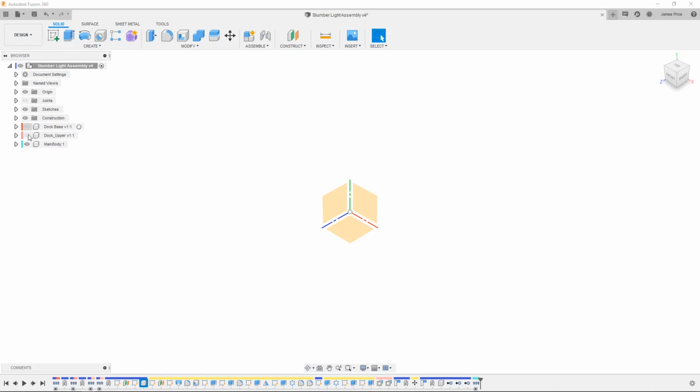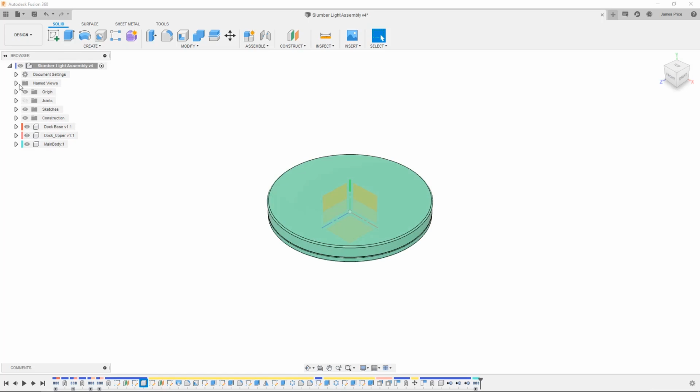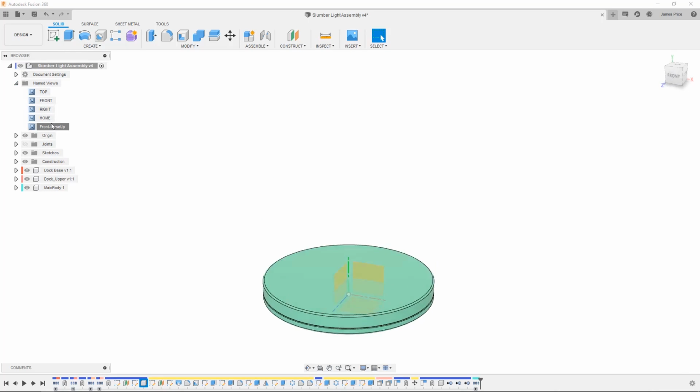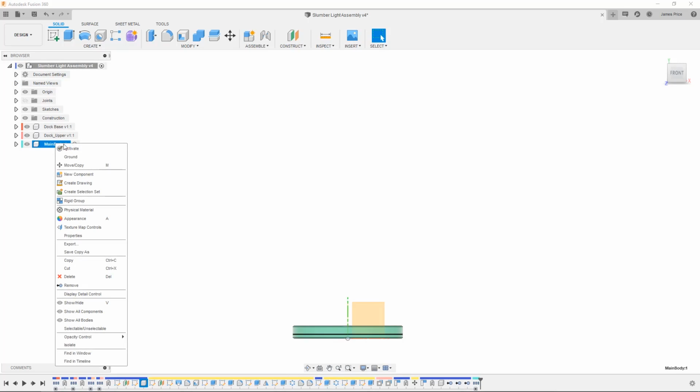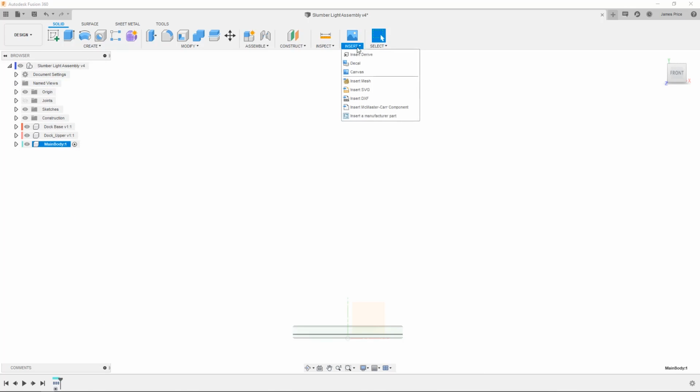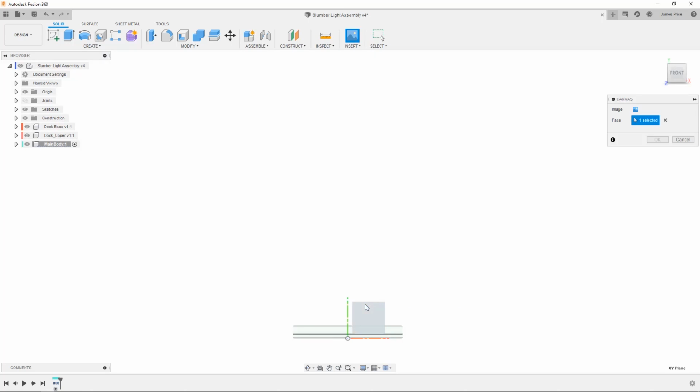When surface modelling, the first thing you may do is attach an image or reference photo to base your design off of. In SOLIDWORKS, you would have used a drop-down menu to find the Sketch Picture command, then follow the process from there. In Fusion, you go to the Insert drop-down and select Canvas. Choose a plane or face and select your image.